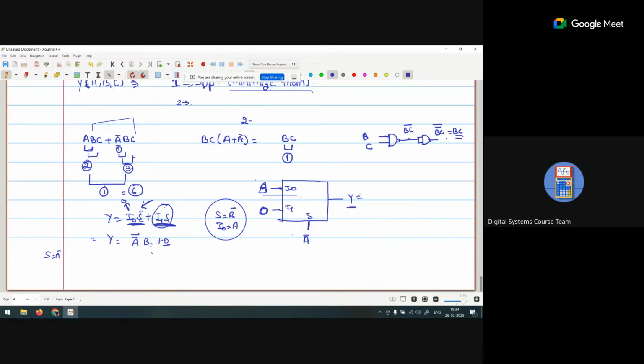That is a different thing. I am not saying that only A and B inputs are available. If I say that only A and B inputs are available, then we use one more inverter. I am not specifying which inputs are available; either A, B, A bar, B bar, both are available. I just design an AND gate. That is the only thing. Clear?